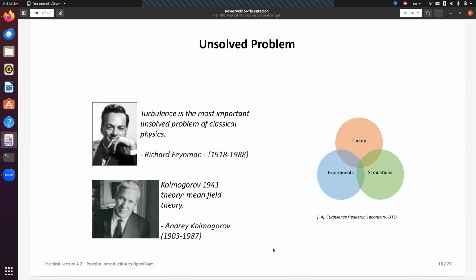For turbulent flow, there are three main approaches with different detailed techniques. One of them is called RANS, Reynolds-Averaged Navier-Stokes, which usually provides the average solution. The next one is large eddy simulation, which resolves some fluctuation of the scales to solve the problem.